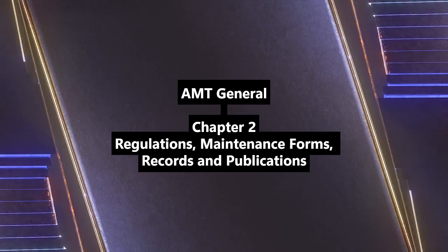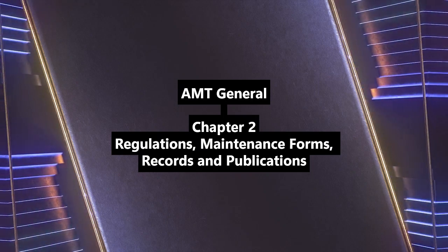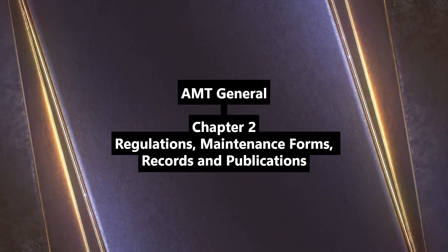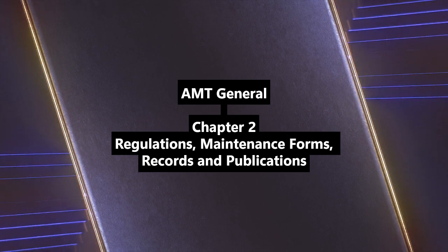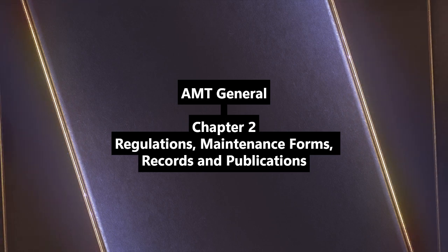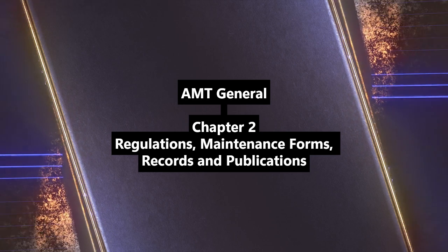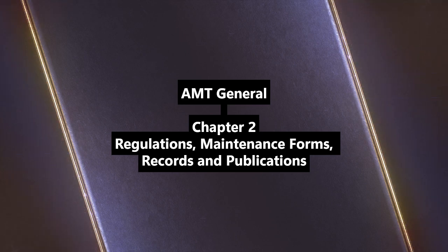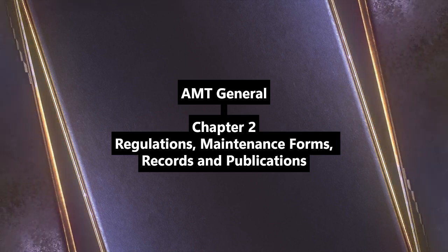Okay, let's talk about those ADs then. 14 CFR Part 39, airworthiness directives. Right. So even with great design and testing, sometimes unsafe conditions pop up during operation. Things break or wear out unexpectedly. Exactly. If the FAA finds an unsafe condition that's likely to exist in other aircraft of the same design, they issue an AD. And that forces owners to fix the problem.